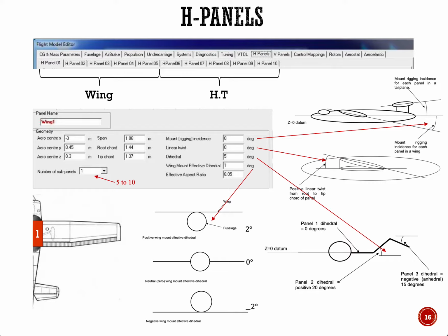Okay. For example, if you put a wing on top, like a high wing, then it feels like you have a dihedral of two, which is why it's a stable configuration. Actually, high wing's a stable configuration. Mid wing is neutral, and you have a low wing, which is like a negative two, which is like having an anhedral. Okay, so this is like a good approximation.